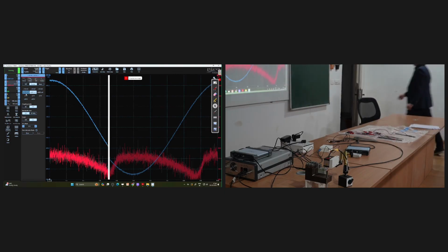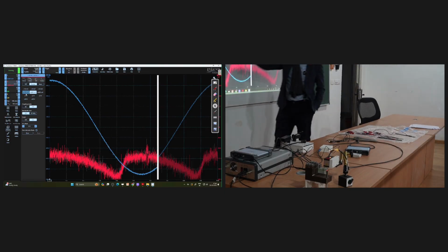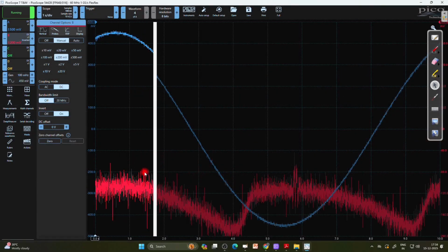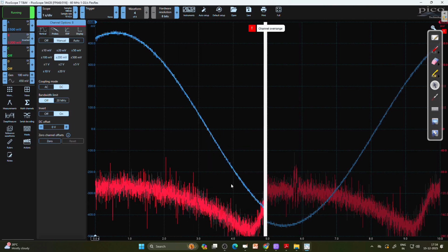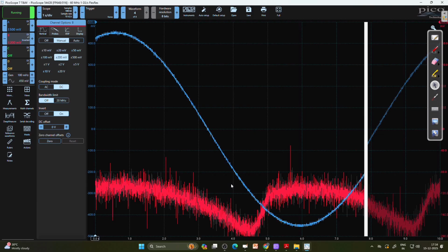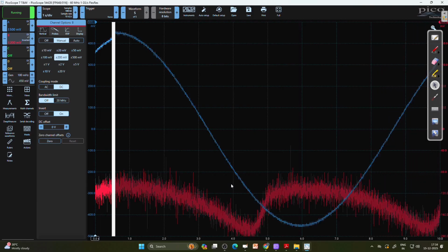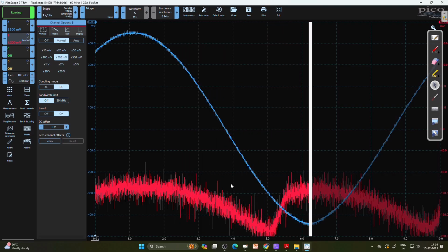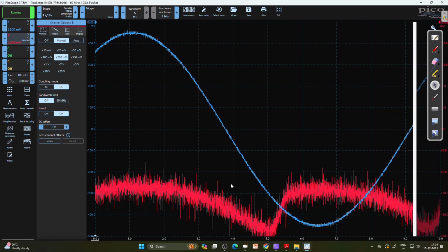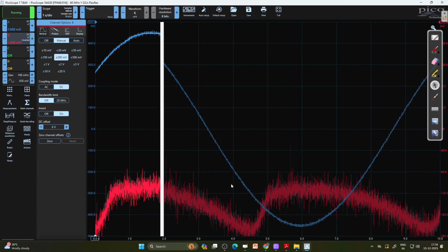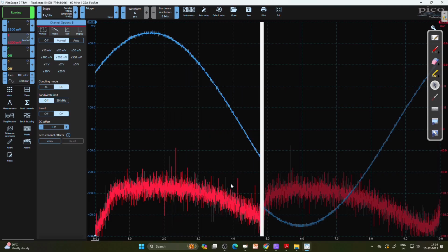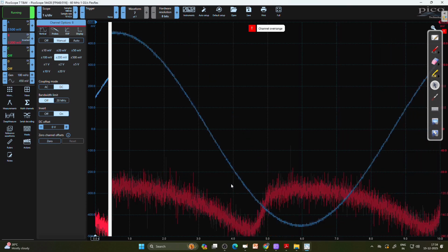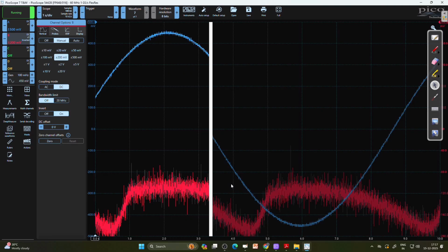And now what you can see, first of all, is that always when, thank you, with the point, right? Okay, so I think I use my hand. So always when we pass 0, shortly after, like here, before we reach the maximum of the blue curve, the polarization changes. So the elongation becomes maximum, and then it changes. And then again, here we go above 0, and shortly after above 0, the elongation abruptly changes. So this is when we reach coercive field strength and when it shifts around.